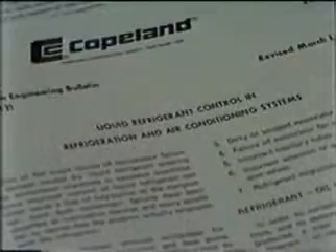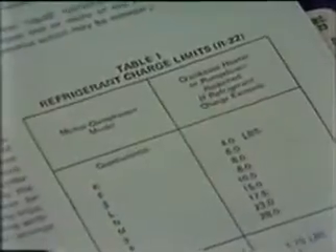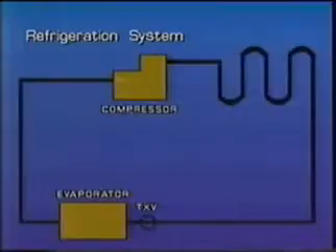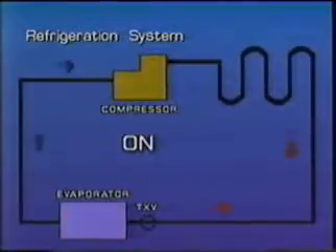And finally, is there more refrigerant charge in the system than the oil can safely absorb during the off cycle? Compressors have a recommended maximum system charge limitation. If the limit is exceeded, the compressor may need crankcase heaters or continuous pump-down systems added. If any situation makes excessive migration possible, and you suspect that crankcase heaters may not be effective, the positive way to prevent migration is to apply a continuous pump-down cycle.